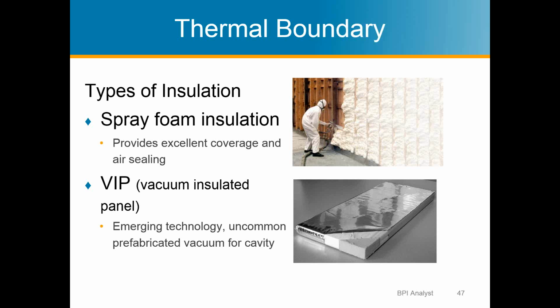But the advantage of pretty much all spray foams is that it can serve as an air barrier and insulation in one. Even the ones that are open cell, which means air could get through them and water could get into them, it's still an effective air barrier, kind of like OSB is an air barrier, even though air can leak through it.